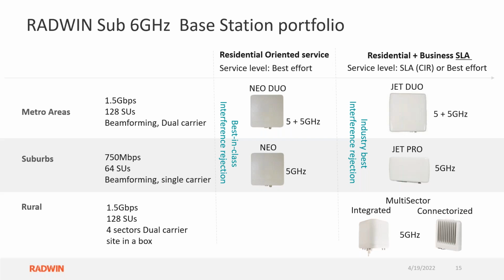Makes it very nice, very clean installation. If you want to make it a full 360, you can add another panel antenna behind it. Now you've got a 360-degree capability with a total of 3 megabits per second and 256 subscribers. Now you're in a place where you've got a very nice, small, tight installation. Takes up very little room on the tower.